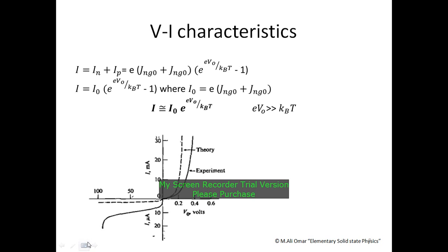So from this equation, we get a relation between the current and the potential. And if we draw this relationship, we get the VI characteristics. The first quadrant represents the forward bias, and the third quadrant represents the reverse bias. In the forward bias, we observe that as we increase the potential, the current will be linear at the beginning and then goes exponential. And let's see what will happen in the third quadrant.